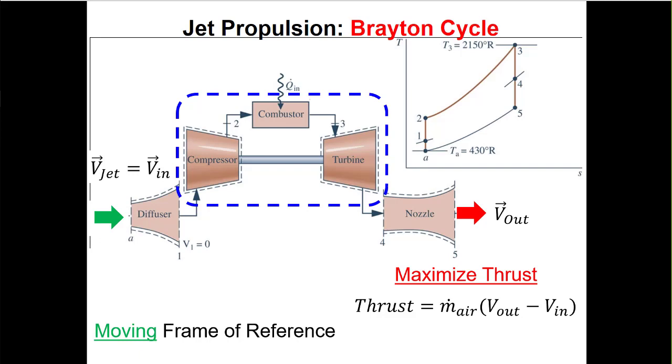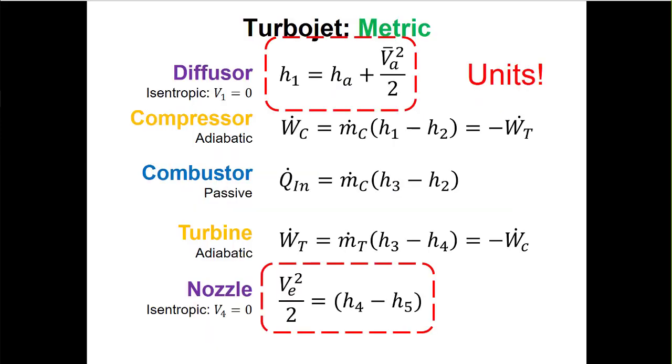This is a Brayton cycle, but it's a special Brayton cycle because the back work ratio is 1. So the power produced by the turbine is equal in magnitude but opposite in sign to the compressor. Another way to think about this is that the net work of the cycle, the mechanical work, W dot, that we calculate, is 0. So the turbine power is equal to the compressor power, but the signs are opposite.